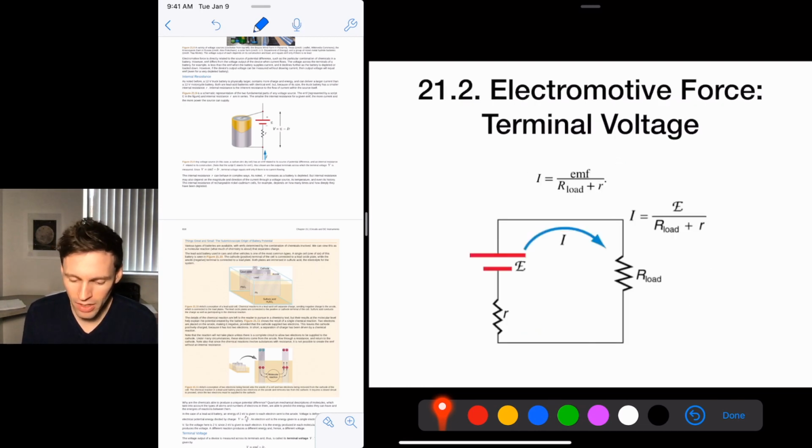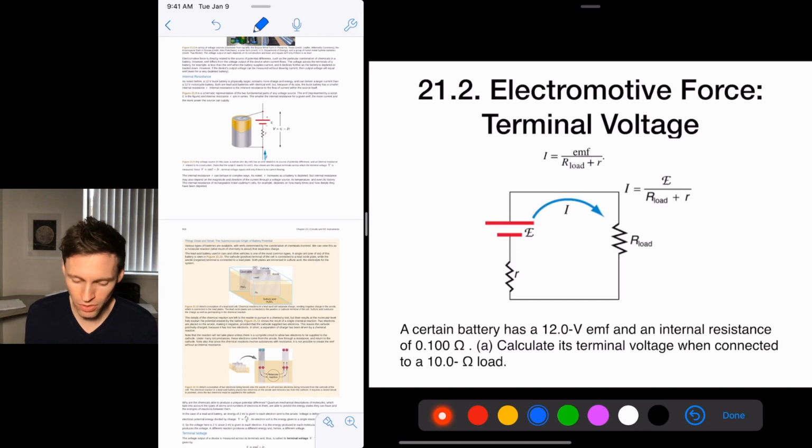So here's your battery, here's the internal resistance of the battery. Notice that this internal resistor and the rest of your resistors are in series, so for V equals IR, you just do R plus r to get them in series. And the EMF, E, is just a voltage, just another voltage, so don't get confused that it's some weird name. It's just V, so you can think of it as the voltage from your battery divided by these two resistors added together. They're just trying to get you to understand that batteries have an internal resistance.